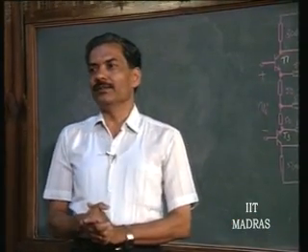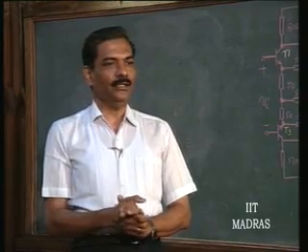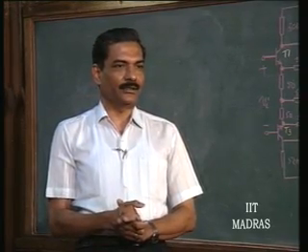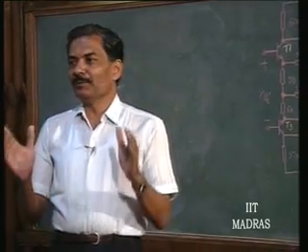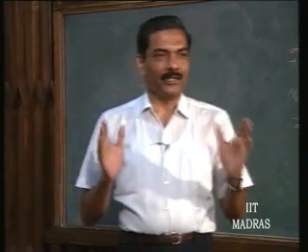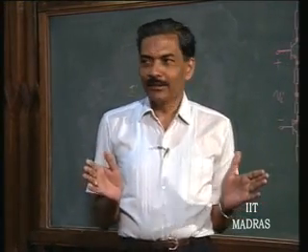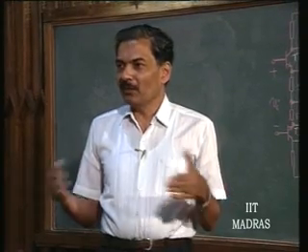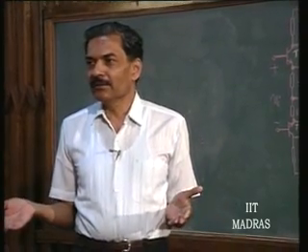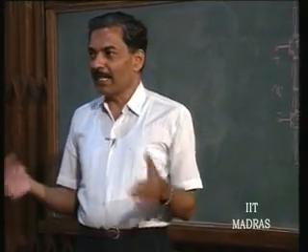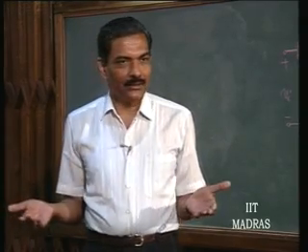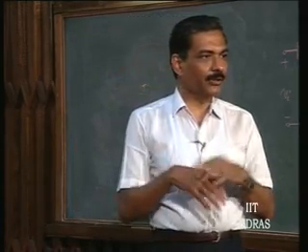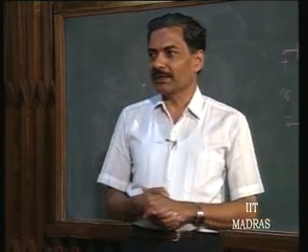Now, can we go to the 3 transistor configuration? By this time you must be totally aware of what should be done, right? It is a routine process now. What are the feedbacks that are valid? Y and Z are valid negative feedback configurations. H and G will turn themselves into positive feedback configurations.